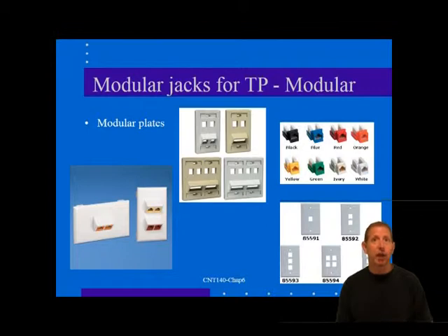Now, while the standards make no requirement for multiple module outlets, they certainly do not prohibit them. And just be careful to include a larger outlet box behind a plate where several connectors may be. You will need a space to coil up all that cable, and the connector module includes the modular connector jack and a terminal mechanism for connecting the cable.